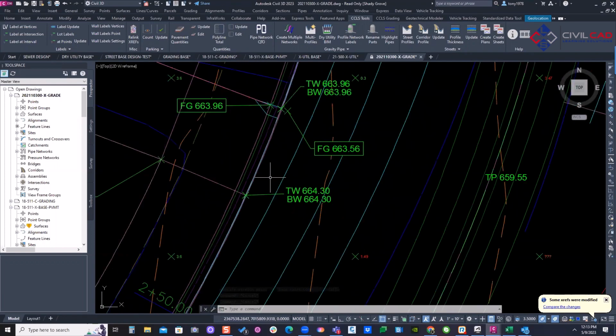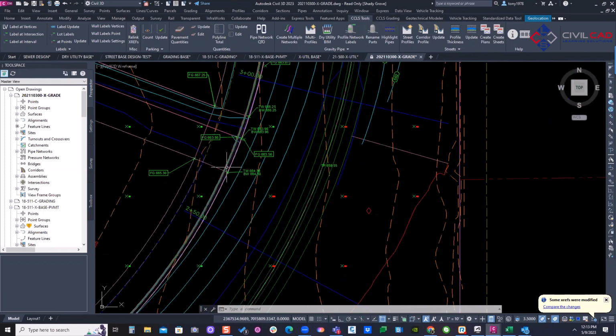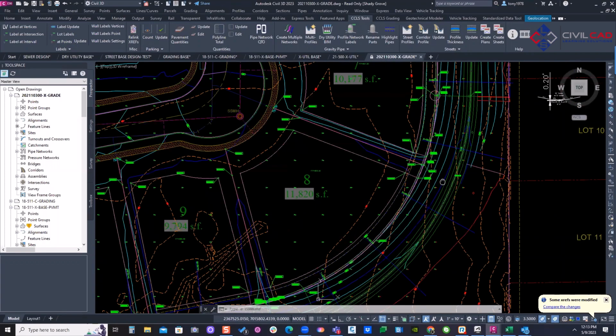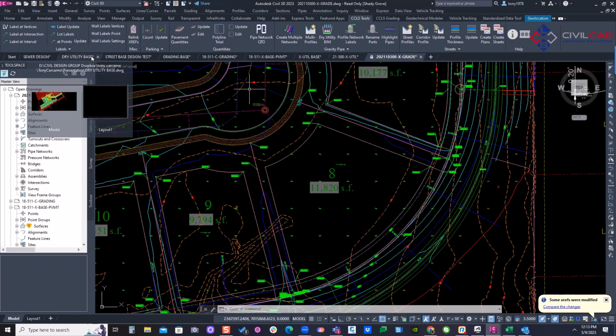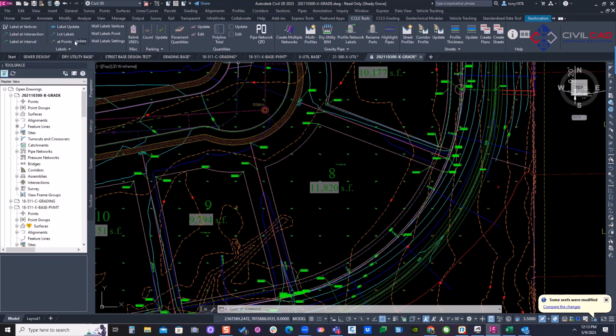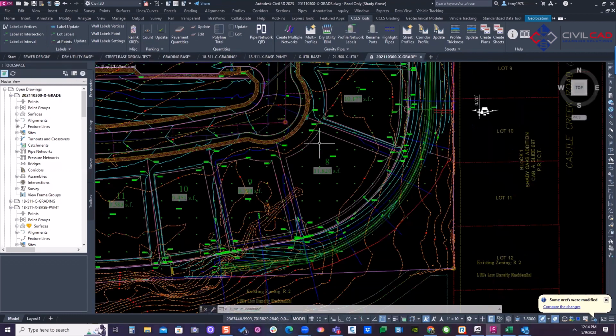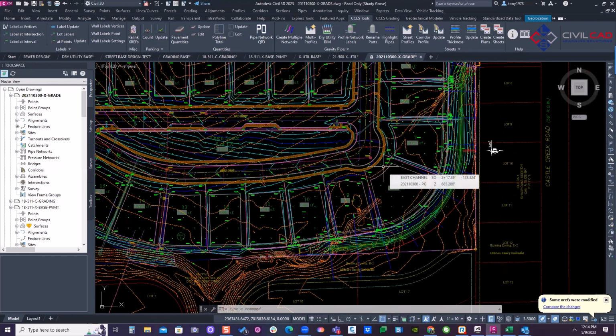Okay. So we had a client that was adding COGO points for surfaces. So we do have an option to add elevation points to all the COGO points in the drawing. That's another feature we just added. There's a COGO point option in there for you automatically. All right, so let's talk about labeling through the sheets now.